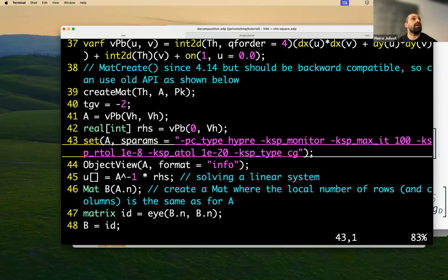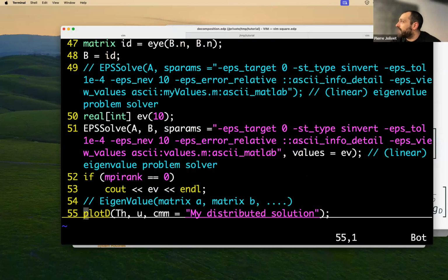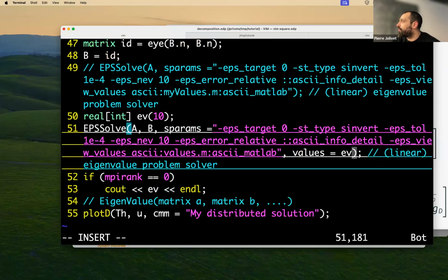And so now let's look at the eigenvectors. Okay, so for the eigenvectors, it's just as before, we need to add a new parameter, okay? And so whenever you have a function in FreeFem which has a named parameter, but you are not sure of the API, you can just input noise. So for example, foobar equal something. Okay, and so here the something will be the eigenvectors.